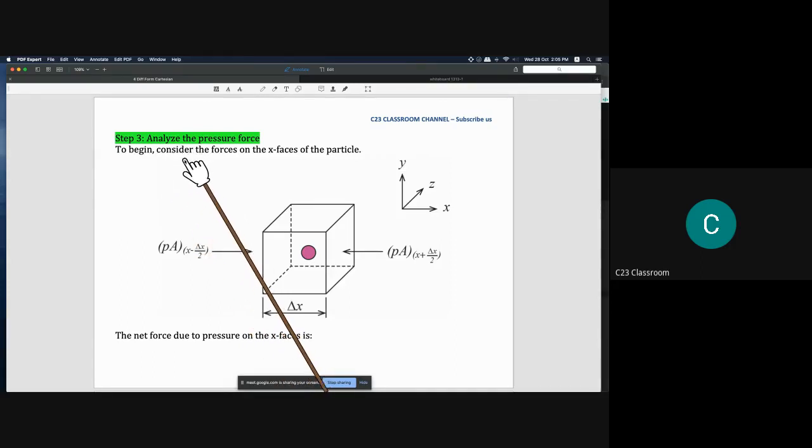So we have 3 forces: the body weight, meaning the weight of the molecule, then the force that comes from the pressure created by the fluid flowing on the object, and the third one is the force regarding the shear stress that occurs from the interaction of molecules on a surface. So we go for the pressure force first.